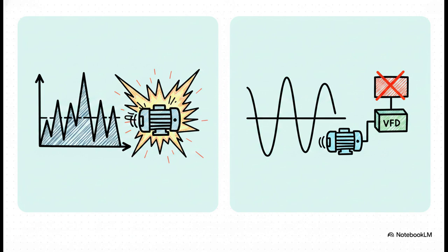But by using the VFD-based PID, the drive modulates the motor speed smoothly and precisely. As demand drops, the motor slows down seamlessly. And the best part? Because the ATV320 has this built right into its own logic, you can completely eliminate the need for expensive external PLC hardware.